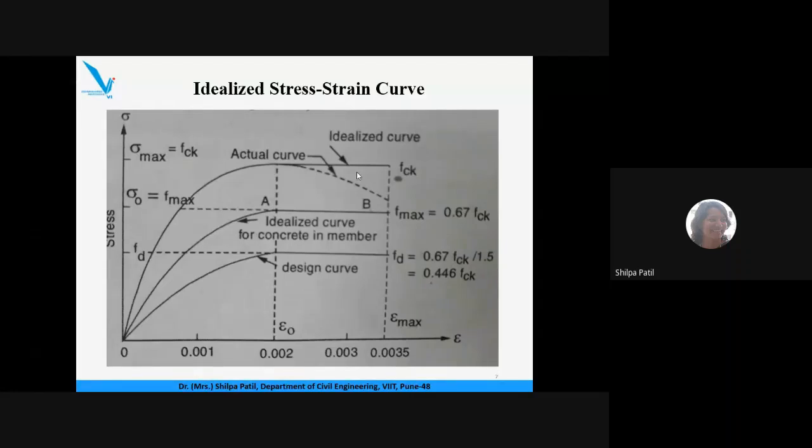If we use the same material for casting a cube and a cylinder, and test the compressive strength of both specimens, we will definitely get a difference in the values. So the shape and size of the test specimen both have an impact on the compressive strength value of the concrete.